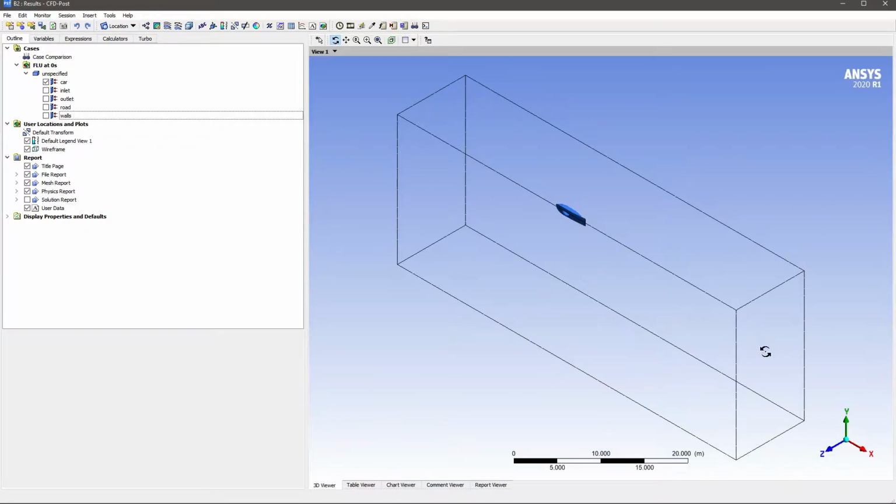Take note of the fact that your coordinate system is very important for how you will use CFD-Post. A lot of the components in this tutorial don't really use things like planes and other locations that involve placing them in the 3D space. But if you have to insert vector planes or vector streamlines at a certain location, then your coordinate frame will be very, very important.